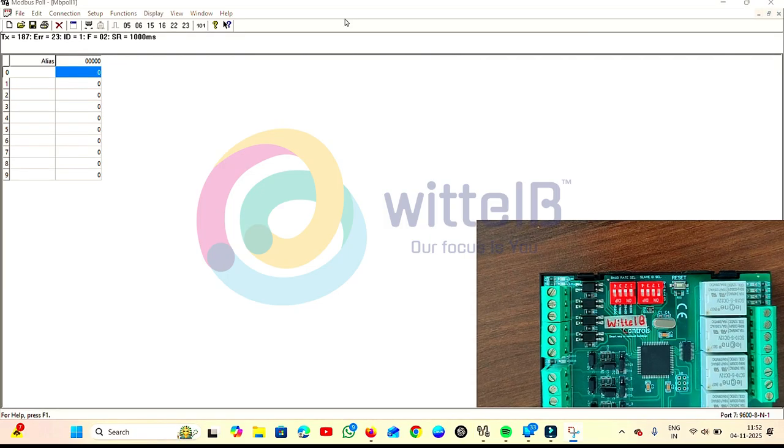In this part of the video, we will see how to configure the slave IDs and the baud rates. So here we have the slave ID and the baud rates. By default the baud rate is 9600 and the slave ID is 1. So now we will go to the PC. See here the board has connected properly with the default baud rate and slave ID. Now I need to change the slave ID to 3.